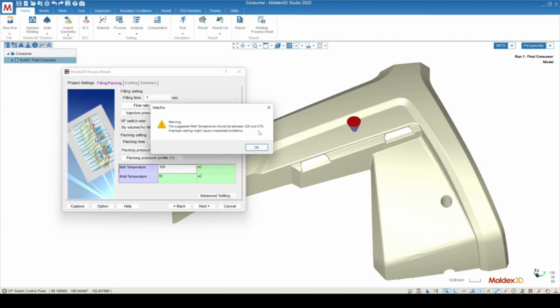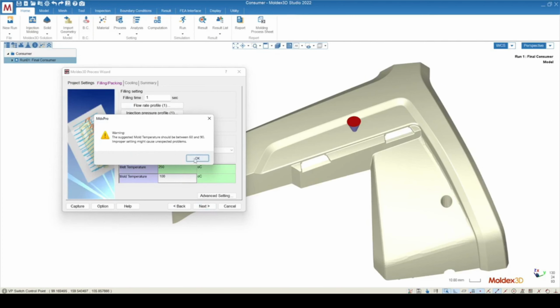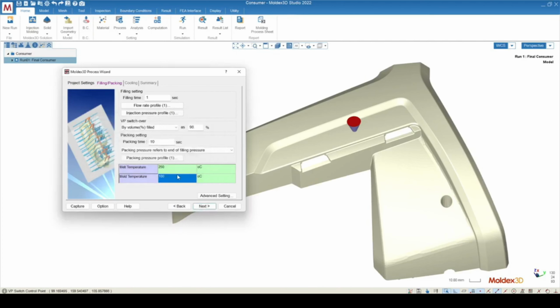If we go too far outside of this recommended range, we can start extrapolating the material data, and not all of the material properties are going to be valid when doing a linear interpolation like that. So it is very highly recommended to stay within this range for the melt temperature to make sure that your simulation is as valid as possible. Especially if you're running a preliminary simulation, you can just use the defaults, and then you can start modulating your melt temperature as needed. The mold temperature, on the other hand, is still soft constrained to a range, but it is less necessary to stay within that range for the mold temperature because this is just the initial condition into the cooling stage.